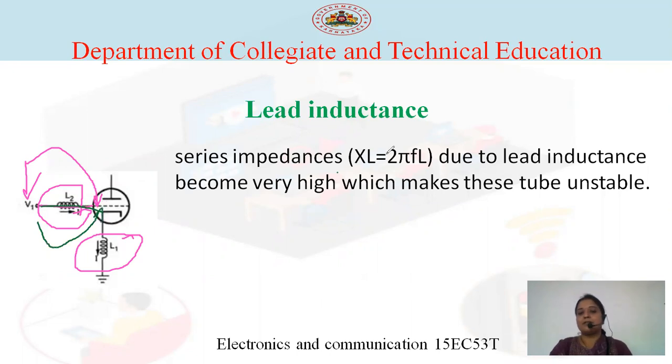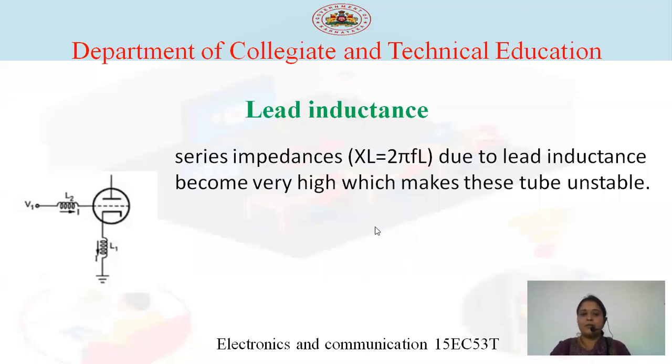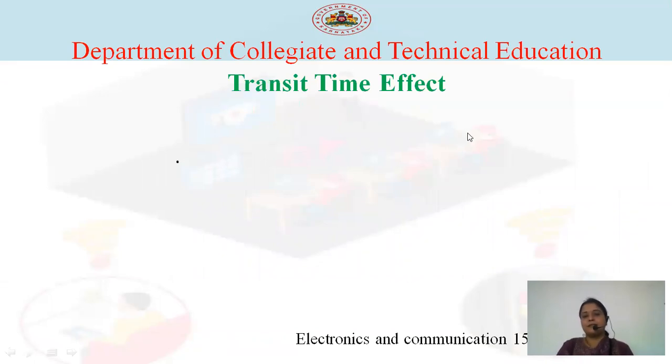But at the higher frequency, what will happen? As the frequency increases, XL also increases. If XL is more, it will be like an open circuit here, and whatever input is applied here is unable to reach the other end correctly. Therefore, this is also one of the major problems, and it occurs only at the higher frequencies. This is called the lead inductance problem.